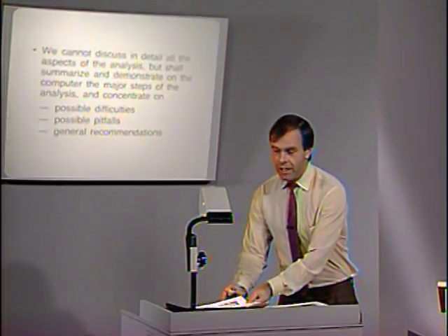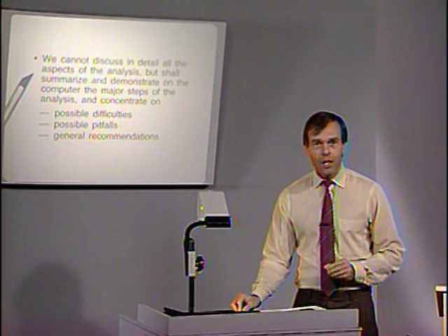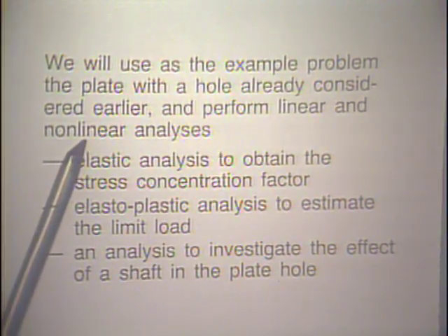We cannot discuss in this amount of time all the aspects of the analysis, but want to summarize and demonstrate on the computer the major steps of the analysis and concentrate on possible difficulties, possible pitfalls, and some general recommendations. As the example problem, we want to use the plate with a hole that we already considered earlier, and we perform a linear analysis and then a nonlinear analysis. Remember, I pointed out in the previous lectures that it is very important to always do a linear analysis first before you go into a nonlinear analysis.